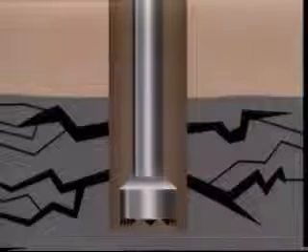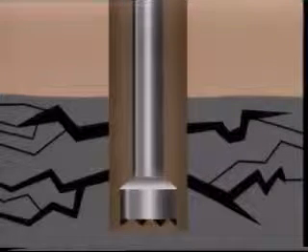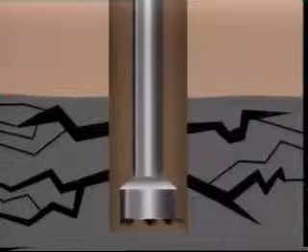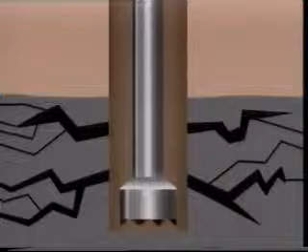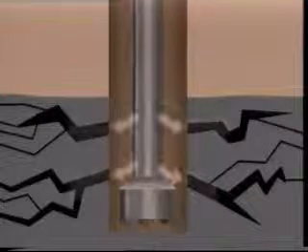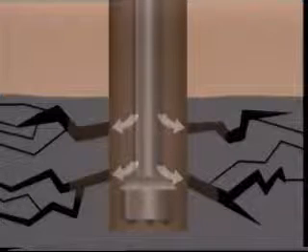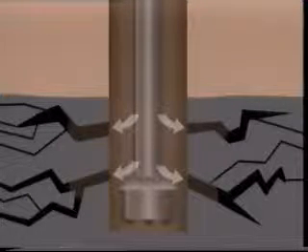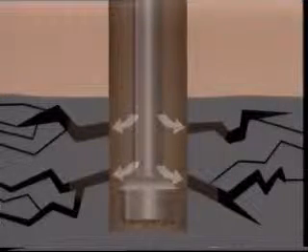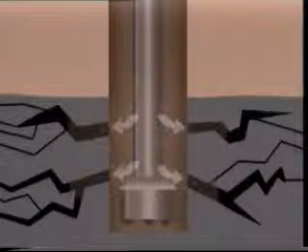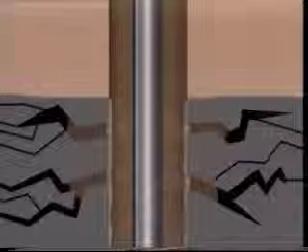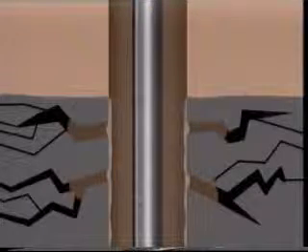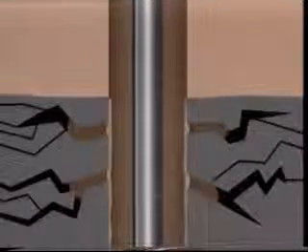When the mud weight exceeds the fracture gradient of a subsurface formation, or if a naturally fractured, highly permeable or vugular formation is encountered, the filter cake formation properties of the mud will not be sufficient to prevent the loss of whole mud to the formation. In this instance, lost circulation materials must be used to physically plug the voids and prevent a dangerous situation which might lead to the loss of well control.